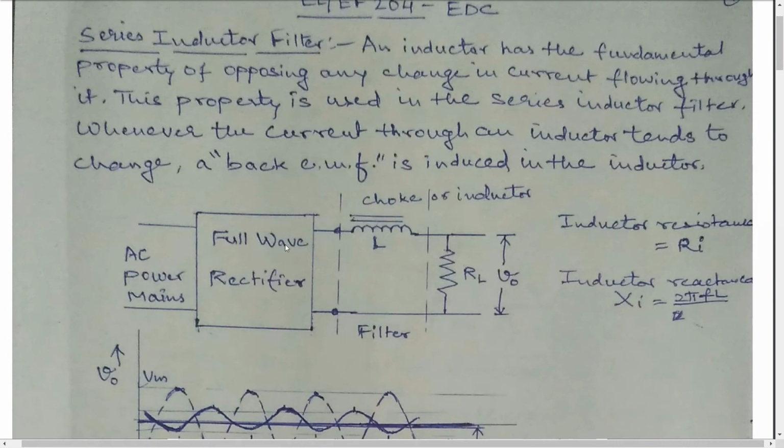Inductive filter is connected at the output of full wave rectifier, which is further connected in series with the load resistance. Series inductor filter. An inductor has the fundamental property of opposing any change in current flowing through it. This property is used in the series inductor filter.